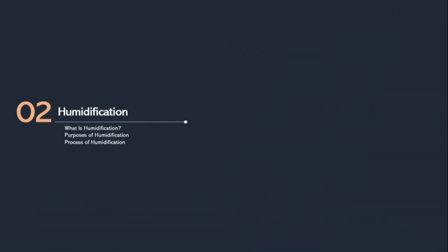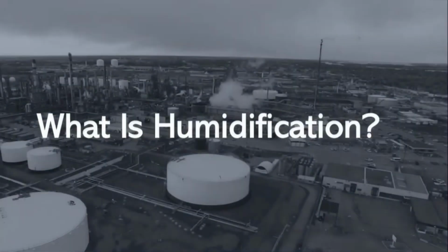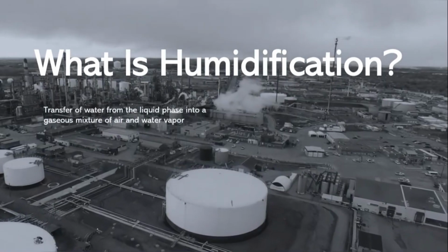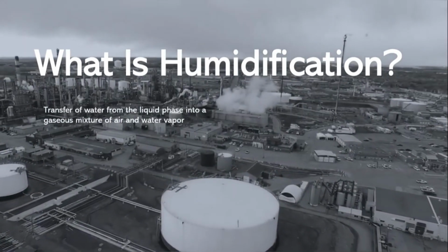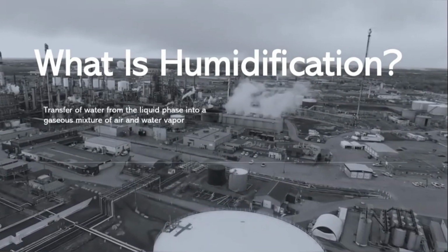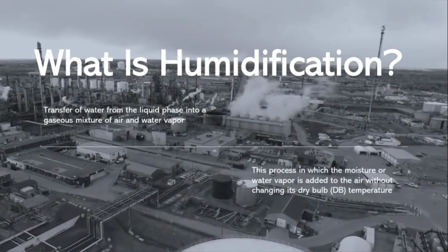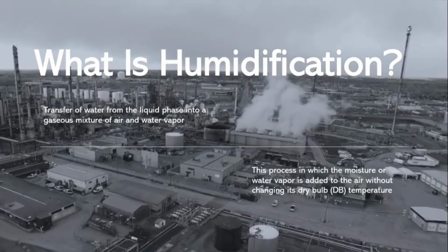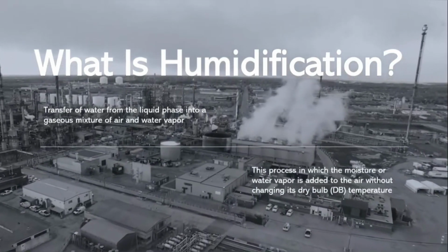Next, we will look at humidification. So what is humidification? Transfer of water from the liquid phase into a gaseous mixture of air and water vapor. This is a process in which moisture or water vapor is added to the air without changing its dry bulb temperature.